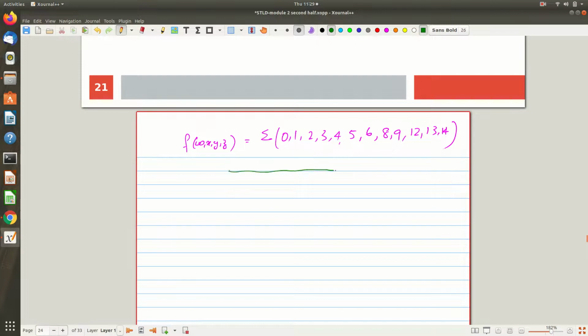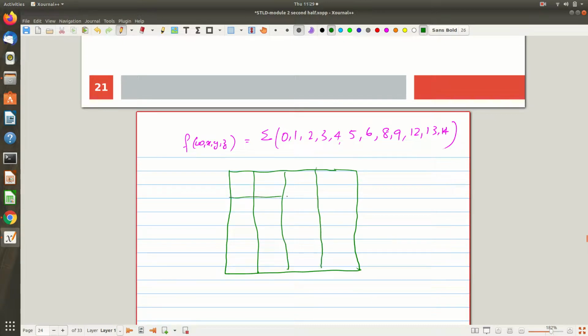So how to draw the table? There will be 16 cells, 4 columns and 4 rows, right? The row number corresponds to wx and the column corresponds to yz, and the labeling is 0 0, 0 1, 1 1, 1 0 in gray code, remember that. Now I am not looking at the labeling, I am directly writing the minterm here. I am not writing m also. So this is minterm 0, minterm 1, minterm 2, then 3, 4, 5, 6, 7. So come here 8, 9, 10, 11, then 12, 13, 14, 15. So hope you understood the way I am writing the numbering.